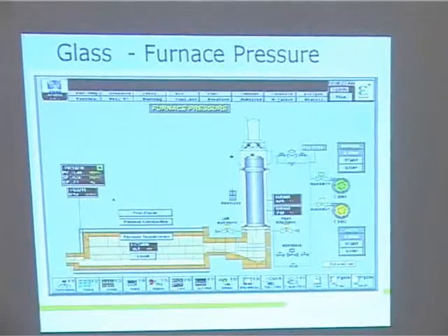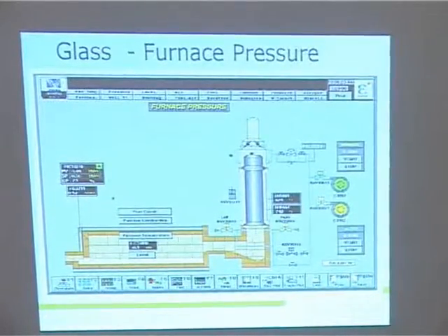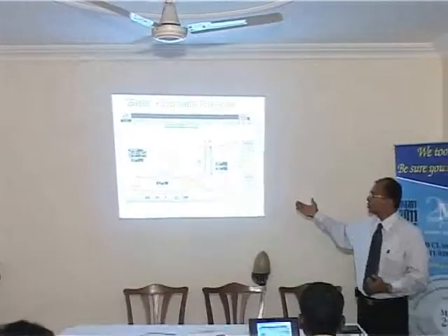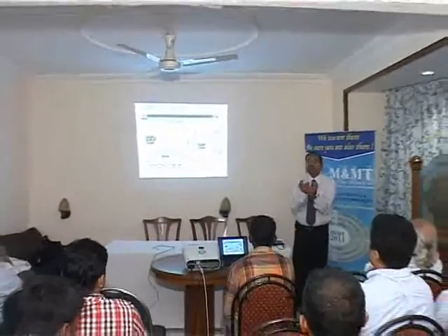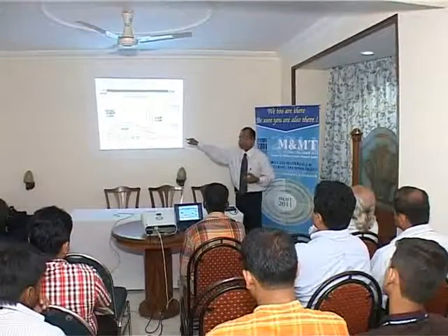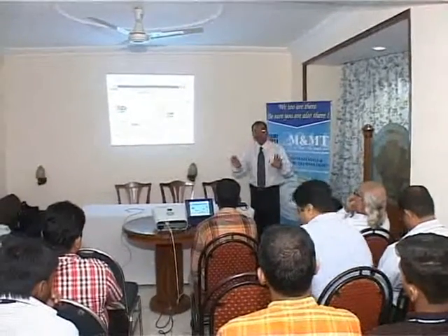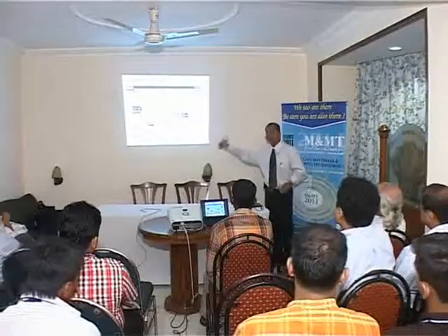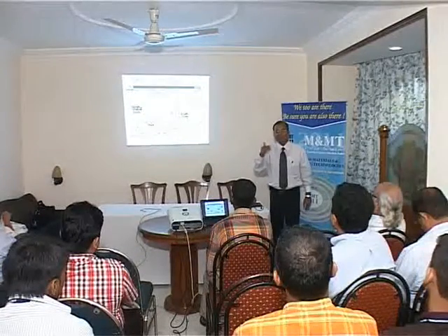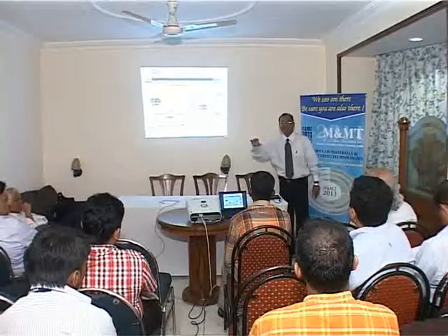Not that this is going to replace your expertise. Please do not take it wrong. You do need the expertise, but at the same time, that expertise is made better use of by ensuring that there are no gross errors because of the graphical, intuitive representation. That is, you can have an interactive interaction. Supposing you feel that there is a draft there, you can actually click into there and get into the PID loop. Even though you are not a PID tuning expert, you have the ability to just get into the tuning mode. The system will go through various sets of PIDs. All you are doing is you can say, okay, there is a uniformity issue, let me just get into the PID loop and play with it.